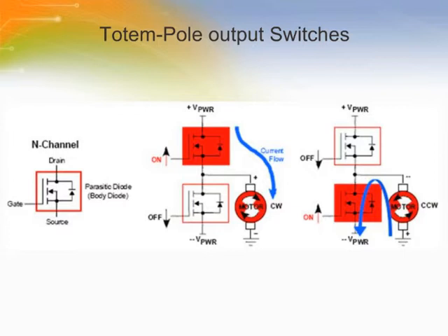In this case, though, both switches require their gates to be pulled up relative to their individual source terminals for turn on. So as to not exceed the maximum gate-to-source voltage rating, two totally separate gate voltage sources must be incorporated. This makes the input control circuitry slightly more complex.